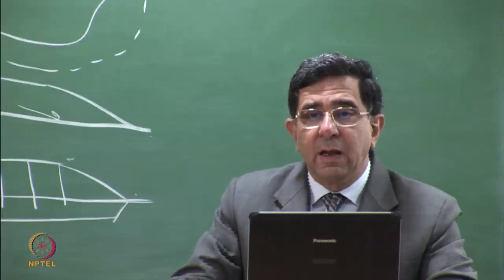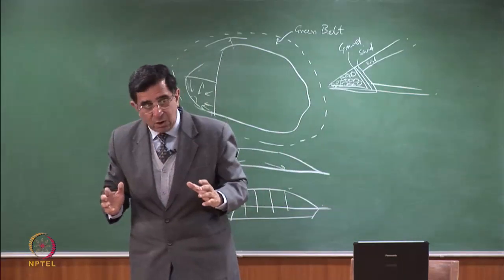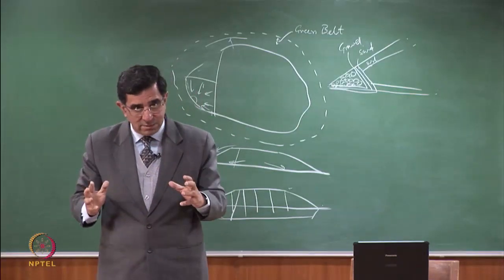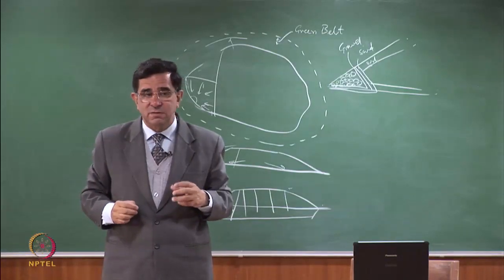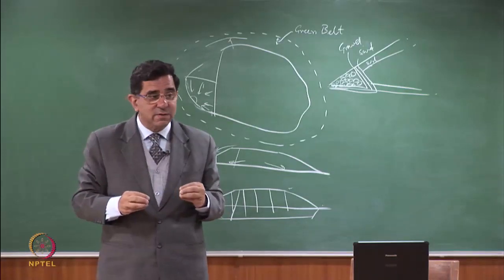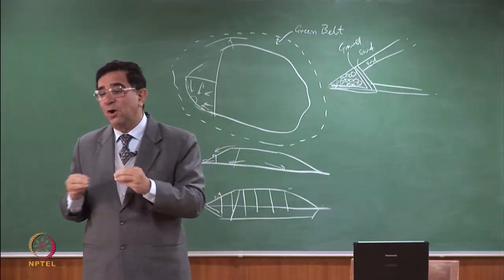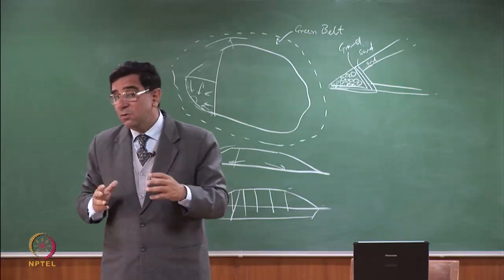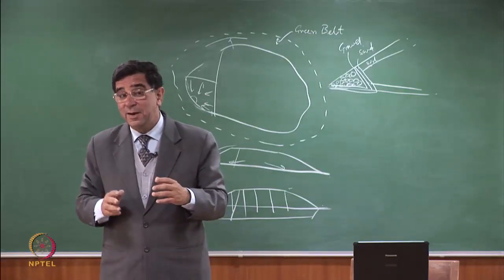So we've done this today. This is a quick wrap up of what we've done so far. How do we evolve the plan? How do we evolve the section? In the plan, where do we place the buildings and where do we place the various infrastructure facilities? And how do we do the phases? In the phases, where do we put the wells, where do you put your leachate wells and where do you put your gas wells? How do you manage the landfill when you are at an intermediate stage?